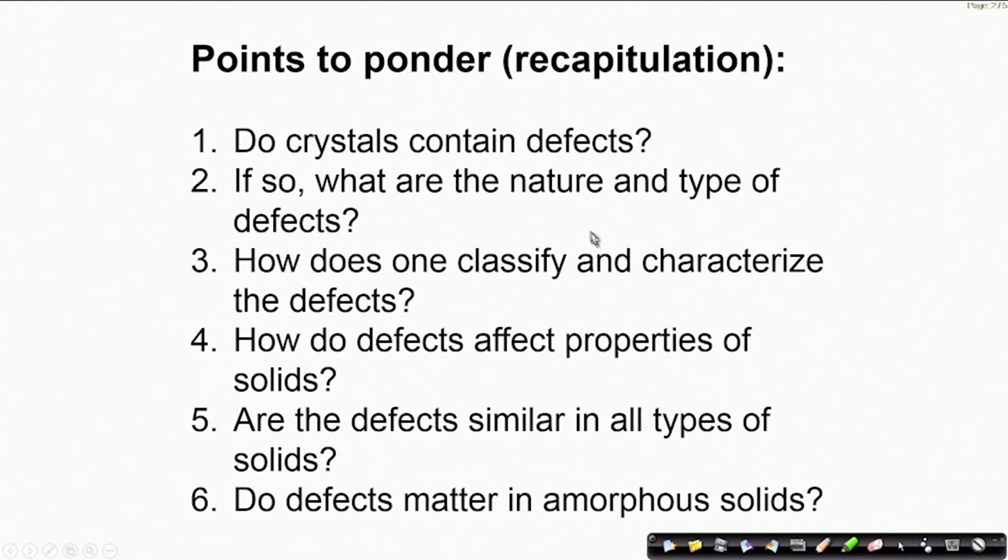So we would now like to wind up and summarize what we discussed. First of all, we do realize that crystals, when we describe them from an ideal point of view, tend to give us an impression as if they are all defect free, but in reality all real crystals will carry defects. And one of the reasons I attributed already is that having a certain density of point defects actually increases the stability of the crystal. Every system in the universe tends to minimize its Gibbs energy, and one way of reducing that for crystalline solids is to have a certain density of defects.